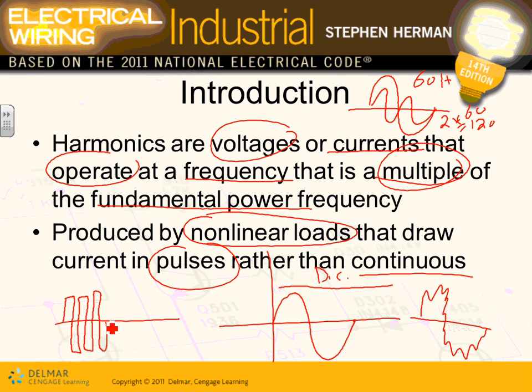So, Derek, every time you convert AC to DC, you create harmonics. Every time you control the speed of equipment using a DC drive or an AC drive, you create harmonics. Every time you put in electronic ballast, which is required by code now, you create harmonics. So it's really a necessary evil. You have to deal with them. There are requirements for how much harmonic you can generate by industry, so you can't just generate unlimited harmonics. They limit the amount that you can generate by manufacturer, and the rest, we as designers have to design a system to handle. Okay, any comments, guys, about the harmonics? Does that make sense, Matt?